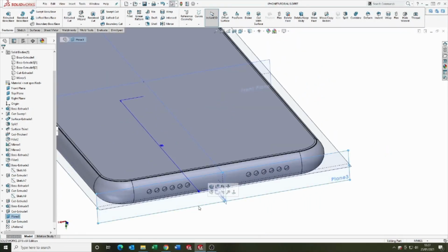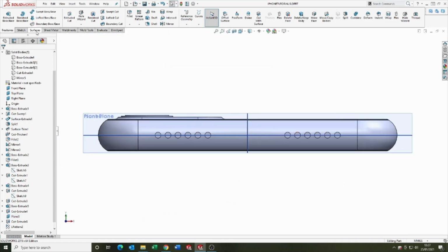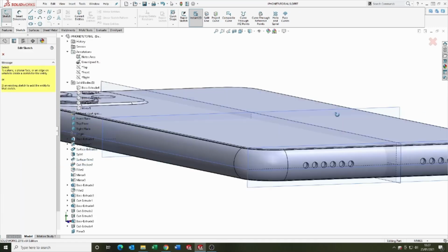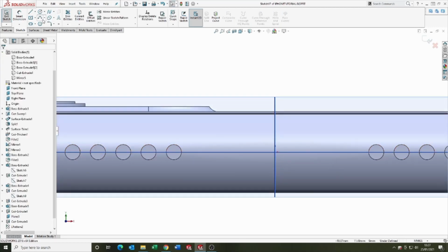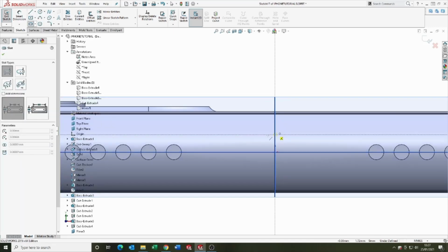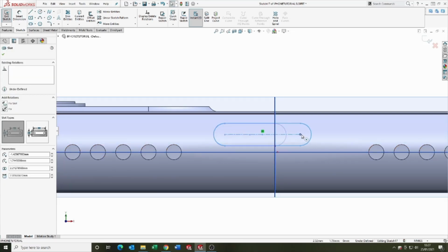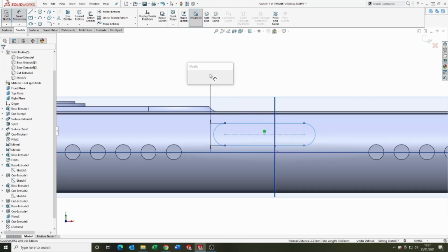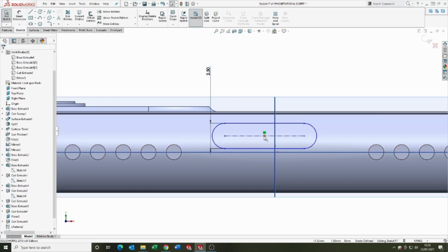And I think now we're just going to look at the charged detail at the bottom. So you're going to select the plane, same plane, and use the slot sketch tool. And if you haven't used the slot sketch tool, it's really nice. You can quickly create slot geometry easily. Just going to make it coincident with the plane.